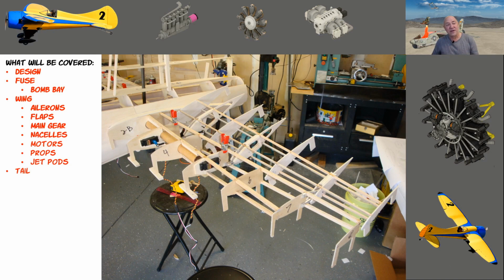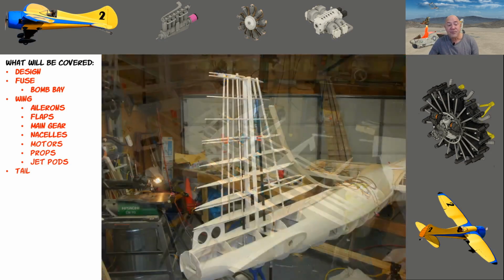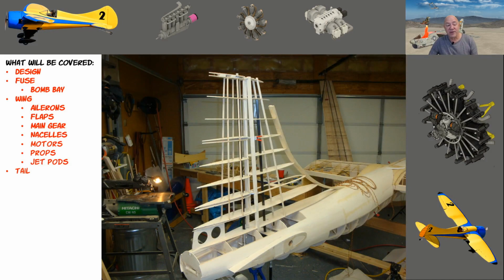And I don't know why the B-36 had such massive elevators, but if you look at it right here, that elevator was massive. And I can't imagine they had pitch instability. But then I started thinking down the road, if they had 2 nukes in there, and they dropped 1 nuke out of the front bomb bay or 1 nuke out of the back bomb bay, how much would the CG move? And did they need that big elevator to be able to trim the flying characteristics of the airplane with that big of a load being dropped from the front or the rear bomb bay? And I bet I'm right on that.